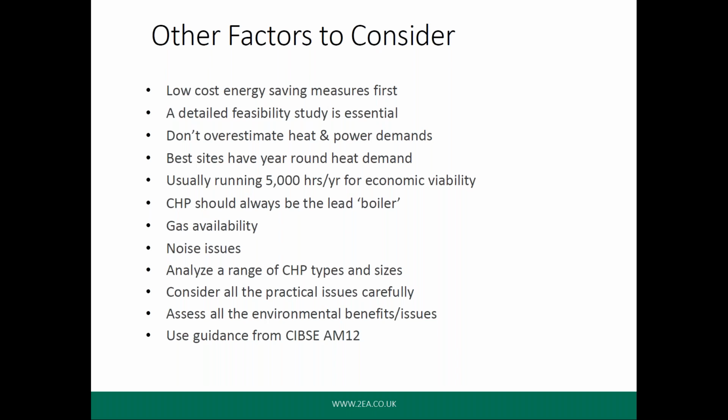Just because the site doesn't have a gas supply at 250 millibar doesn't mean that a larger combined heat and power unit is out of the question. The lack of pressure can be solved by the installation of a gas booster. These are a simple solution provided the gas supply is capable of supplying the volume of gas necessary. This needs to be checked with the host site, and probably then with their gas supplier, as they're unlikely to know.